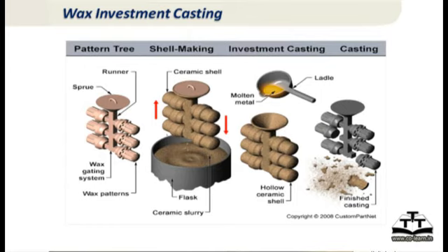Investment casting is usually good for small parts, so you don't want to make one part per mold. You solder these wax patterns around a tree. This tree, which later becomes the gating channel in which you pour the metal, also acts as feeding for the casting. We'll look later at what gating and feeding are, but for the moment, we are attaching these wax patterns around a central sprue which looks like a tree with branches.